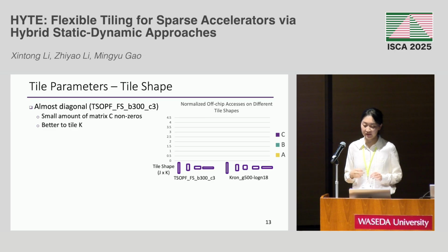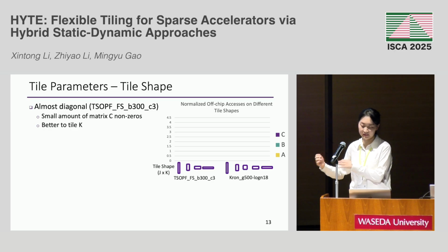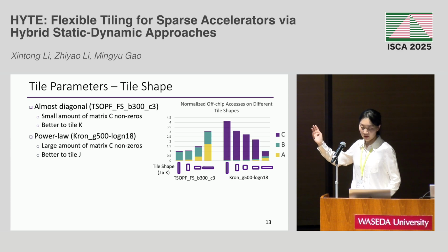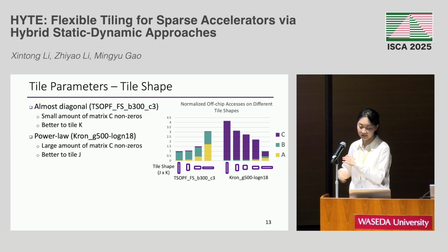Additionally, different tensor computations involve different sparsity levels in tensors A, B, and the output C. For sparse output tensors, tiling along the K dimension, which is not related to C, only incurs little extra C access and is the ideal selection. However, for denser output tensors, tiling K incurs a high cost in accessing C repetitively, so other dimensions are more suitable.